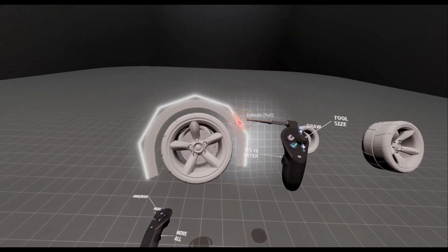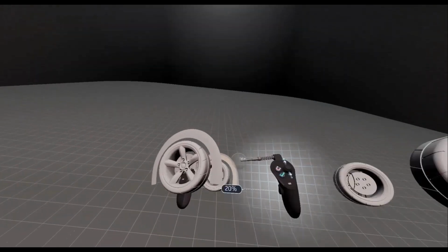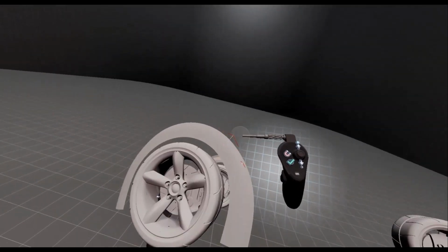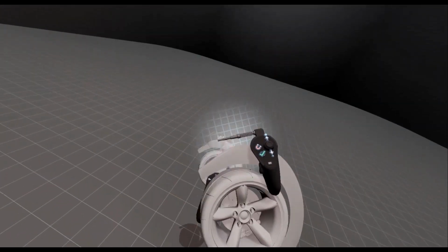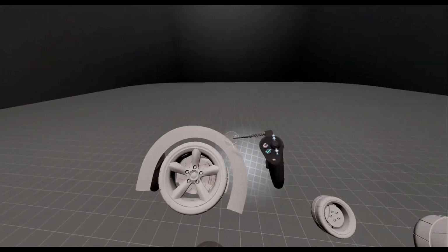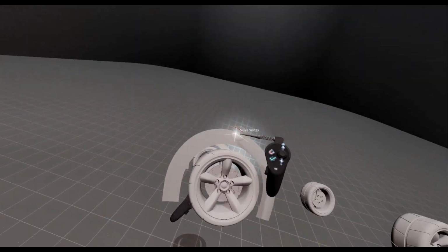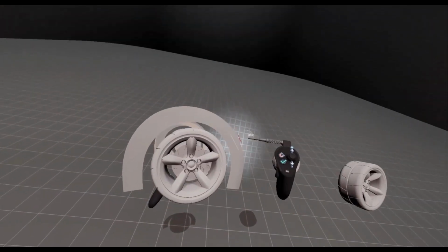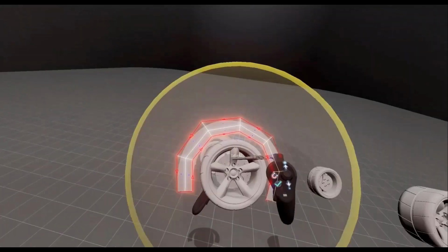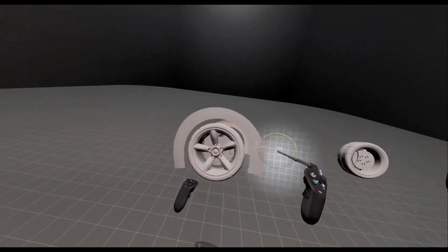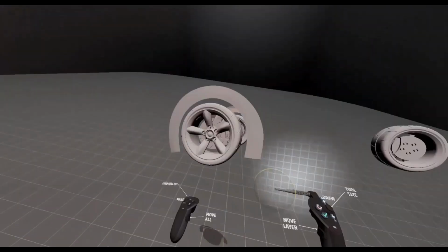Now here's another example where if you select an edge and use your thumb pad, you can select the edge you're working on, or you can select the entire group of edges in that edge loop. So this designer is now making some changes to the number of CVs here to get them in alignment the way that she wants them. And then she's going to select that outer edge again. Oh, sorry, she's going to duplicate.